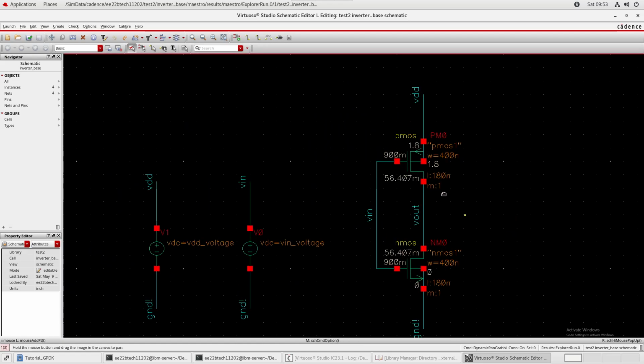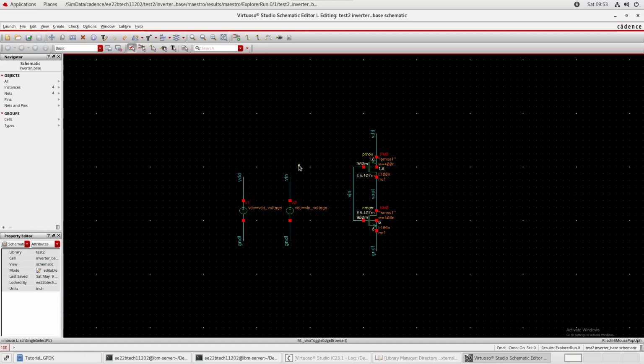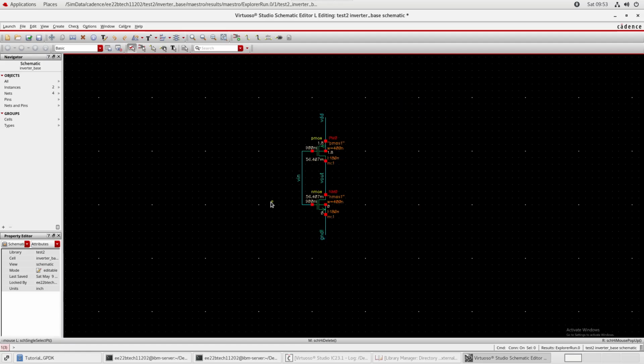Now that these basics are covered, go into how to make a schematic. We have the schematic. This is a really bad way of making schematics, because whenever you have a design which you want to put on a chip, all the schematics that you're making, if they're not a test bench, if they're the design, they should not contain anything, absolutely anything, which you can't put on the silicon, which you can't realize in actuality.